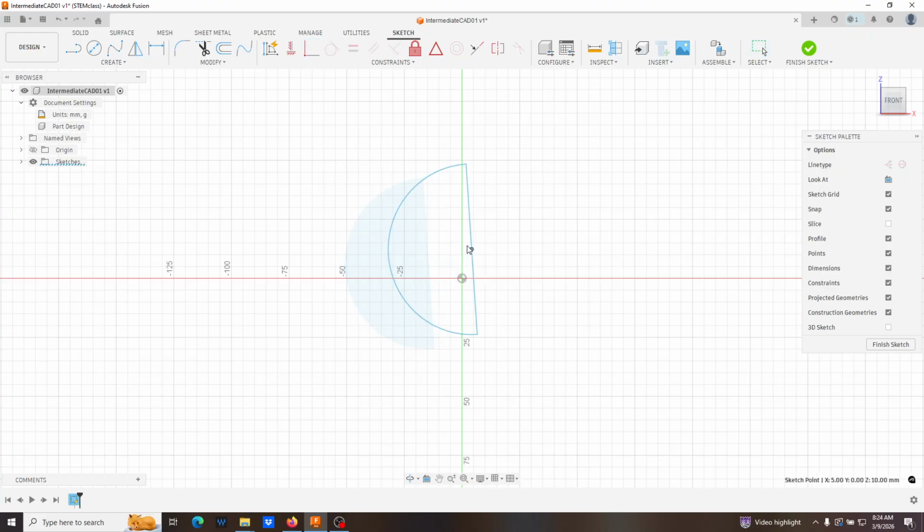Okay, so now when I move all of this around, I'm going to click this center point here to this center point here, and then I'm going to hit a coincident constraint to lock that in place. Then I'm going to hit escape to move out of my constraint. You'll see how my cursor is black. I'll hit escape. Then I'll select this line, and then I'm going to go to a horizontal vertical constraint. All right, and then I'll hit escape again. Again, you want to remember when you're working in CAD tools, you're generally switching the mode that you're in. And so the escape key is always a good friend to get you out of that. Escape to get out of this.